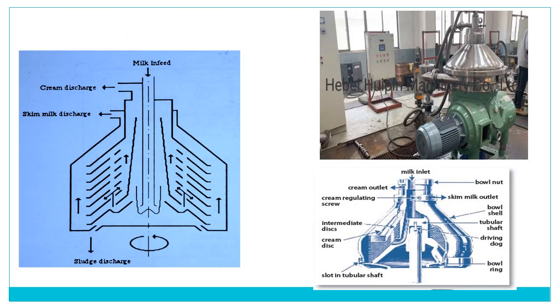Here we can see the diagram of a cream separator. At the left side, you can see the central entry of the normal milk, and inside this cream separator there are many hat-shaped discs. Now after the milk goes inside, due to the centrifugal force, the skim milk part, being heavier, gets separated and